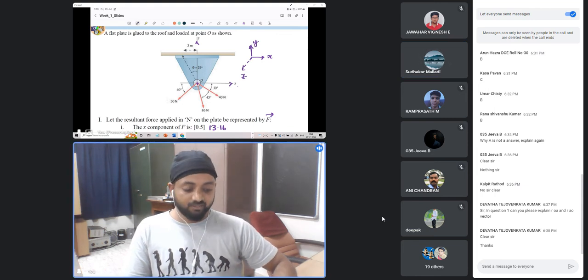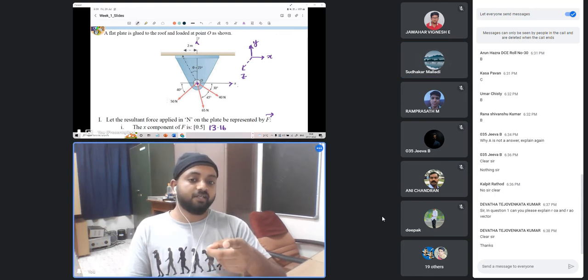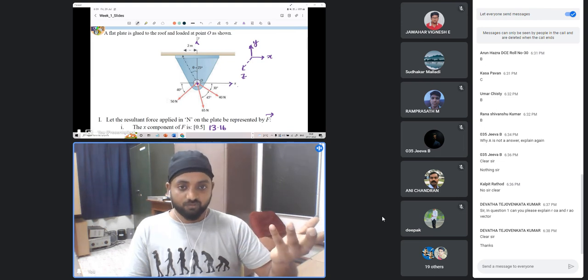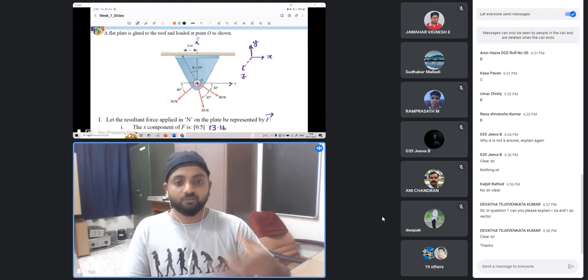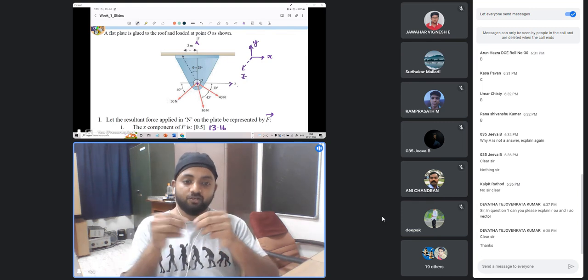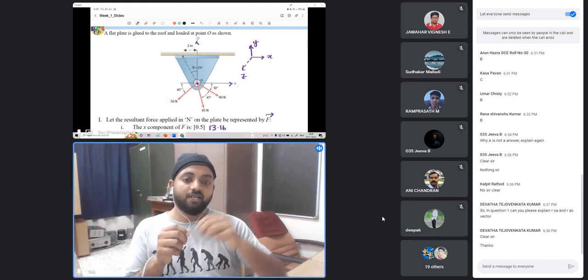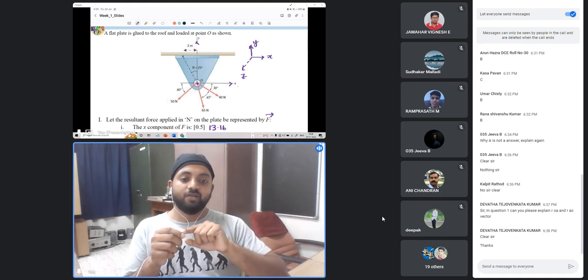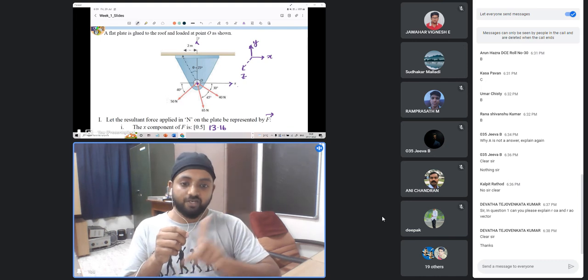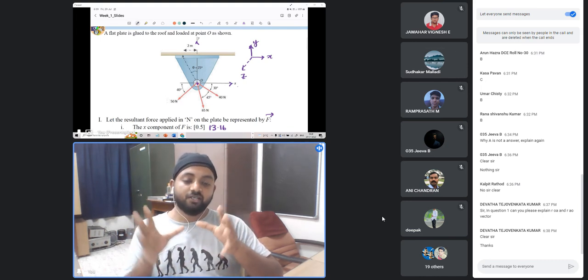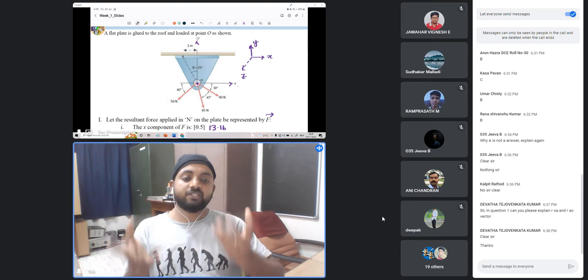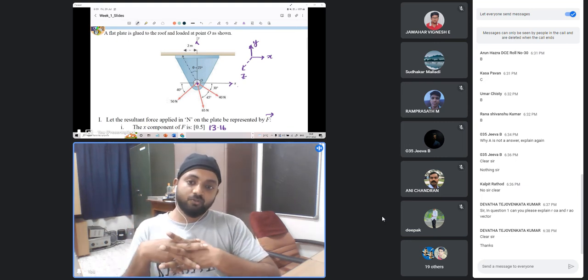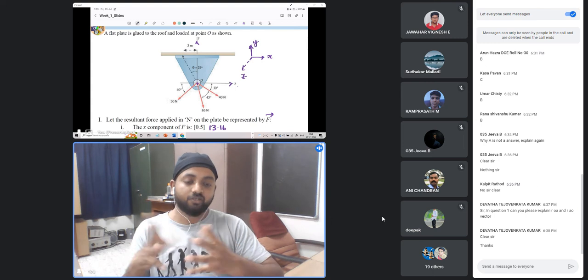Yes, exactly. So here it so happened that at O, all the forces applied were concurrent. So if you have to shift, R cross A, R is 0. So a 0 vector cross anything is 0. So there is no moment. Whereas if you had to split this, if this 40 Newton I had to apply somewhere else, but I had to calculate it at O, then there will be an additional couple because of the existence of R. You can just consider that in a concurrent force system, R which has to exist is 0, so you don't get any moment contribution.